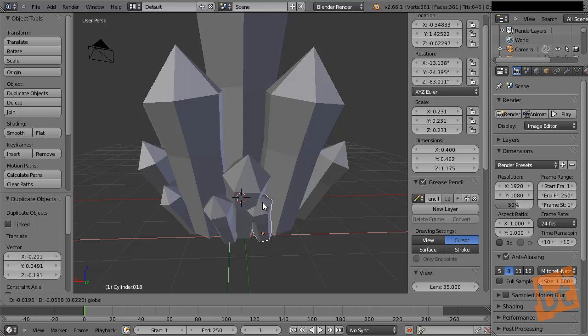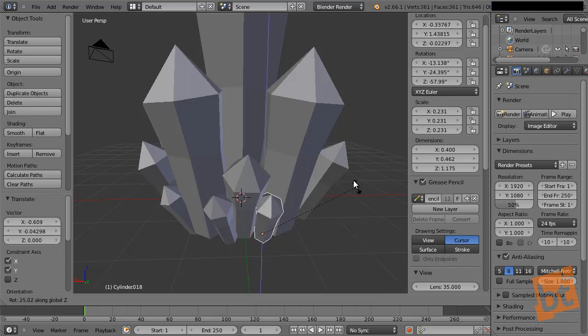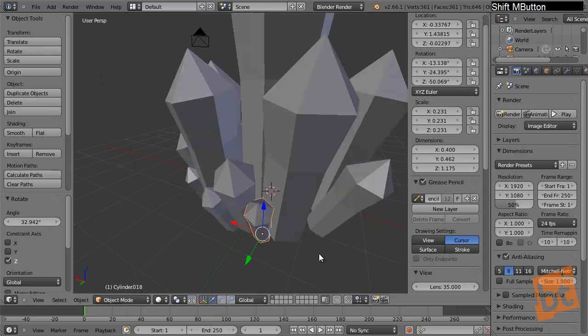So you can now slide it through the floor and the Z axis of the object won't be affected. Now you can release the Shift key and it will keep moving, because if now you press Shift again, it will be moved precisely, all right, with the precision movement, which is something that I love about Blender.